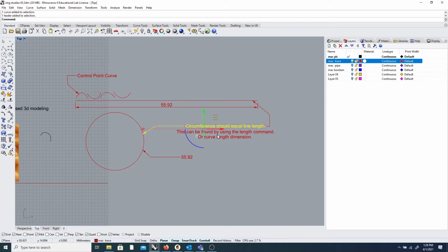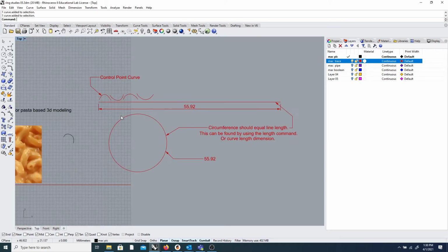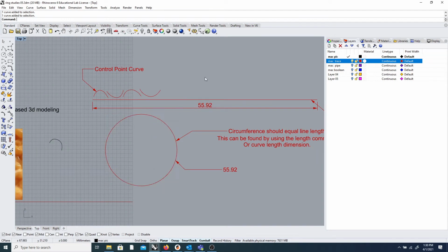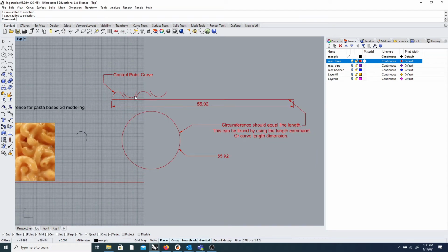Right? So I utilized that curve here to create some other geometry. I utilize the circumference of this to get a length. So I'm going to model things straight on a line, and then I'm going to use that distance to wrap them around that geometry. So I'm using curves to control and drive my geometry, the way it's going to look in the end. Okay? So this is where I started. So I use the circumference distance to draw my curve distance, right?